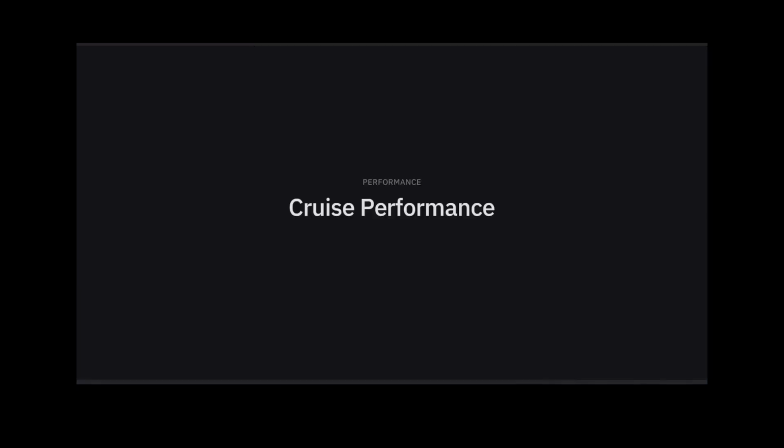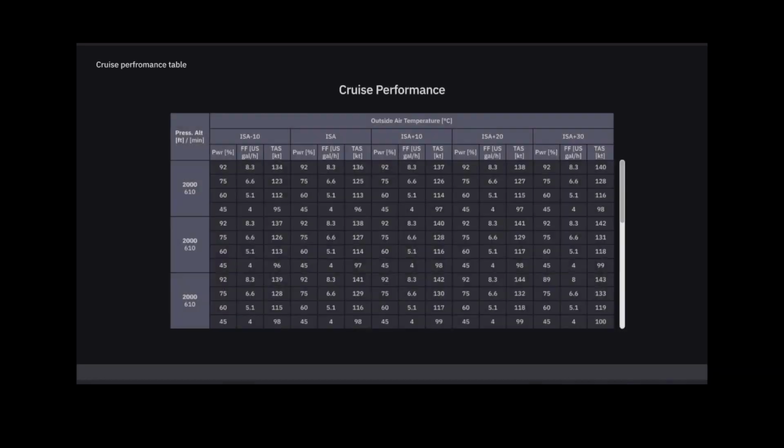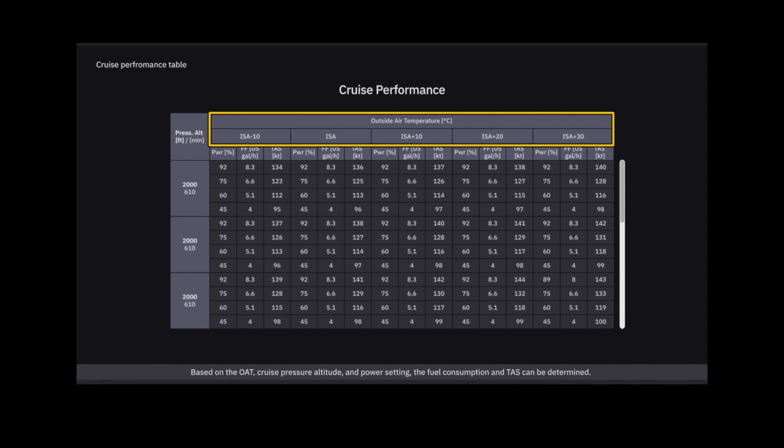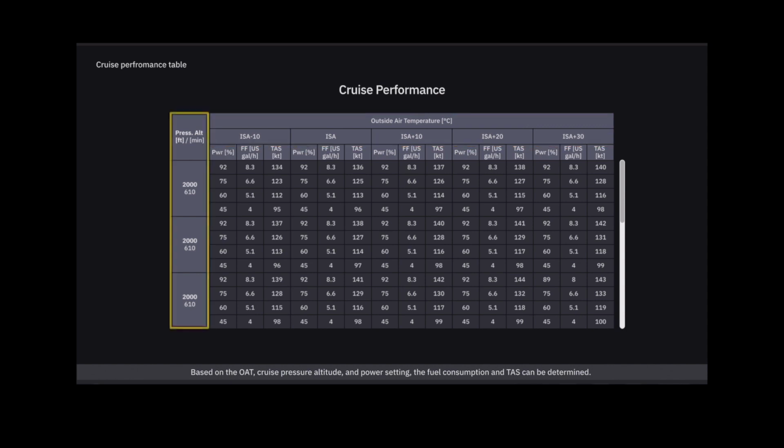Cruise performance. To determine the cruise performance of the DA40NG, the table shown on this slide is used. Based on the outside air temperature, cruise pressure altitude, and power setting, the fuel consumption and true airspeed can be determined.